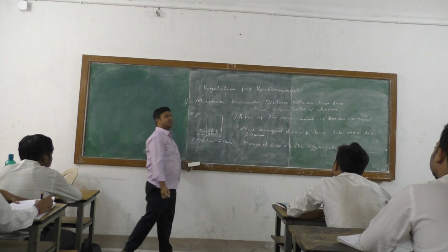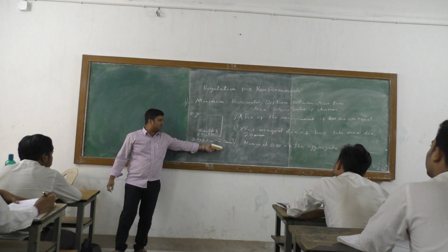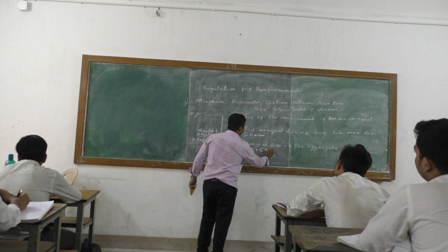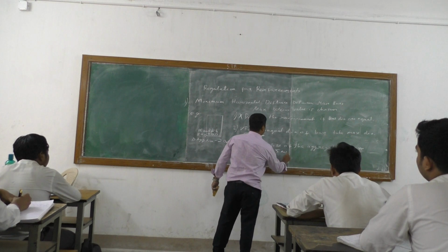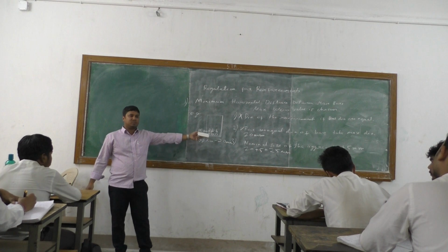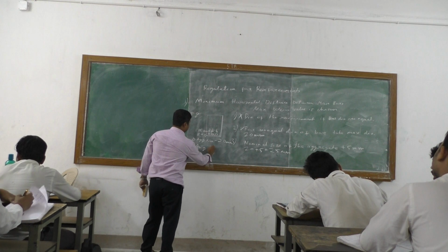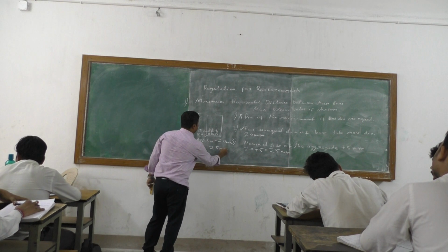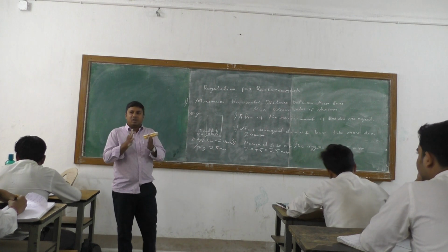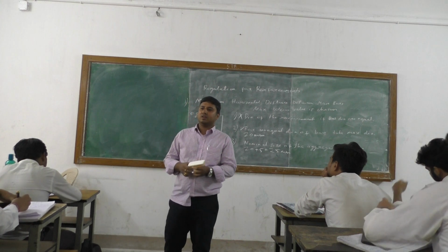Okay. Now from the third criteria, what will be the value? You tell me. The nominal maximum size of the aggregate is equal to 20. So 20 plus 5 is 25. So what value should you take? From these two, we have to take the maximum size. So 25 is the maximum size. So the answer is 25 mm. The nominal maximum spacing between the aggregate in the reinforcement is 20. Understood?